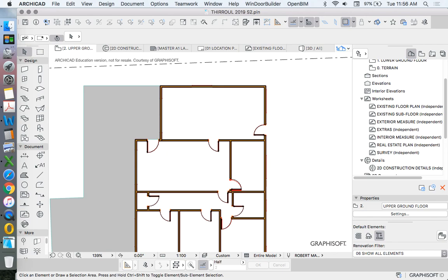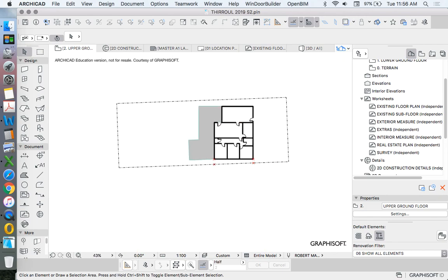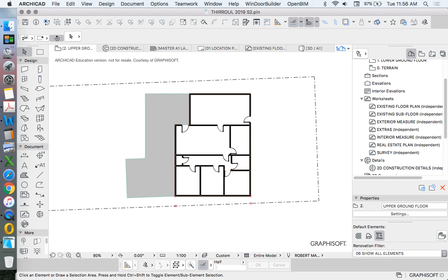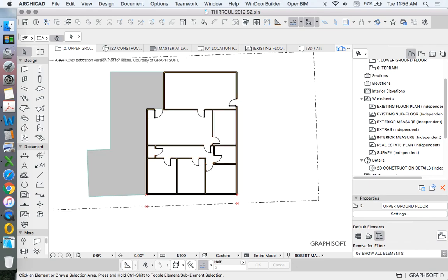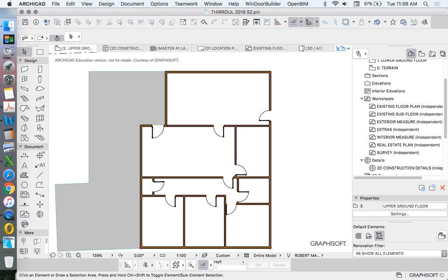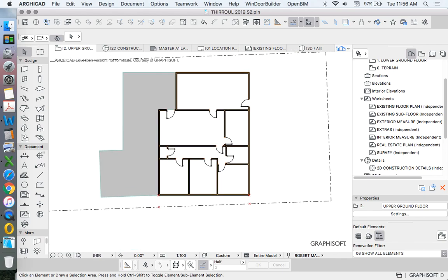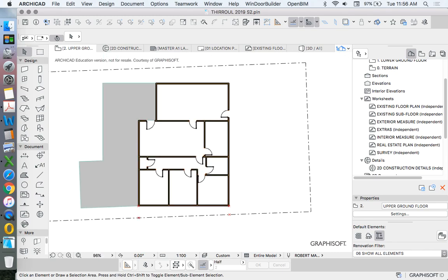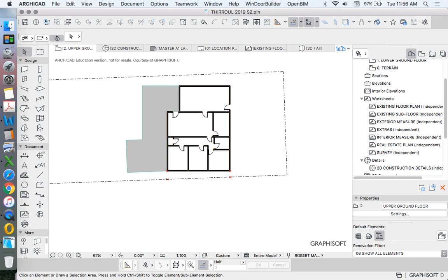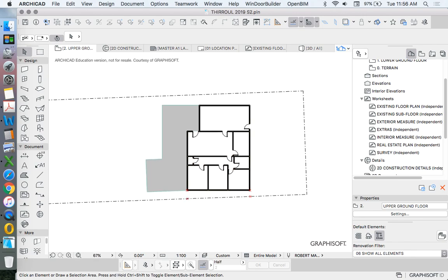So that's placing doors. If you can just place doors into your model for now, then you're going to be able to roughly use that for space planning. We've missed a few. There's a few others because there's some sliding doors and there's some windows, but at least if you do that many doors, you at least know how to get in and out of most of the internal rooms, and that's a good way to start. So let's start this now, place those doors, and then we can add more different types of doors and windows in because the settings of those are slightly different.